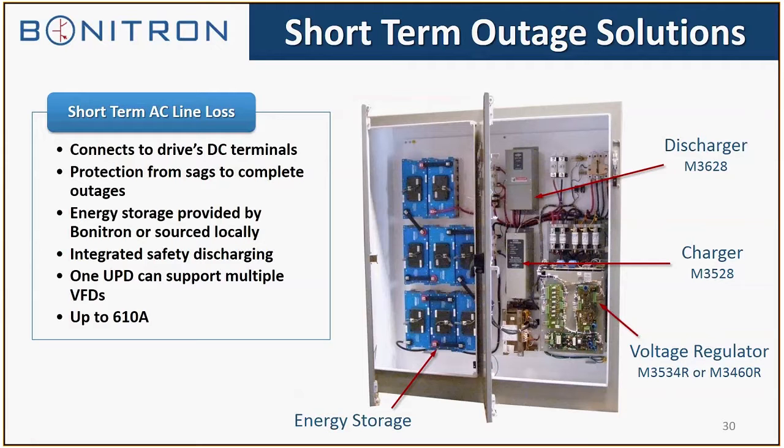The energy storage is provided by Bonitron or sourced locally. Like with UltraCap solutions, we really would like to provide the energy storage, but if the customer is adamant about having a good UltraCap connection, then we'll look at the specification of the caps they're using, make sure they're going to work with our system, and we do leave that option open to the customers to source their own energy storage. Once again, on the right-hand side, you see the components: the discharger, which discharges the caps, the charger, and the voltage regulator booster. It will either be the 3534R or the M3460R. On the left is the UltraCap energy storage.